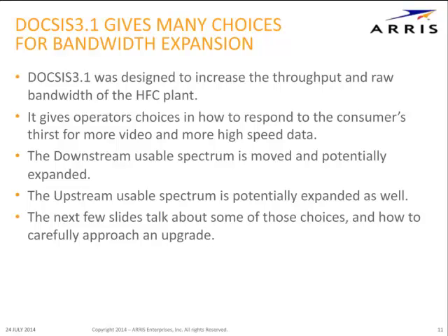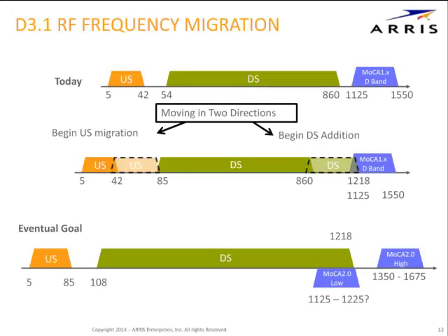And I think I'll just go ahead and show the next slide. So if you look at what DOCSIS 3.1 proposes as part of the overall standard today, similar to George's slide again, you've got upstream from 5 to 42, and downstream from 54, and different people will be at 750, 860, some people up to a gig.